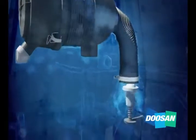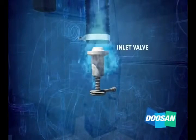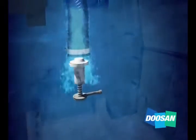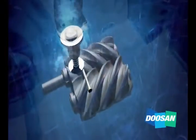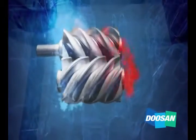Filtered air continues through sealed piping to an inlet valve that controls the volume of air reaching the air end and prevents oil from reversing towards filters after shutdown. Next, air enters the air end, which is a fixed displacement pump that uses two helical rotors to compress air. As the rotor screws turn, they form a partial vacuum which sucks air into the helical rotors.